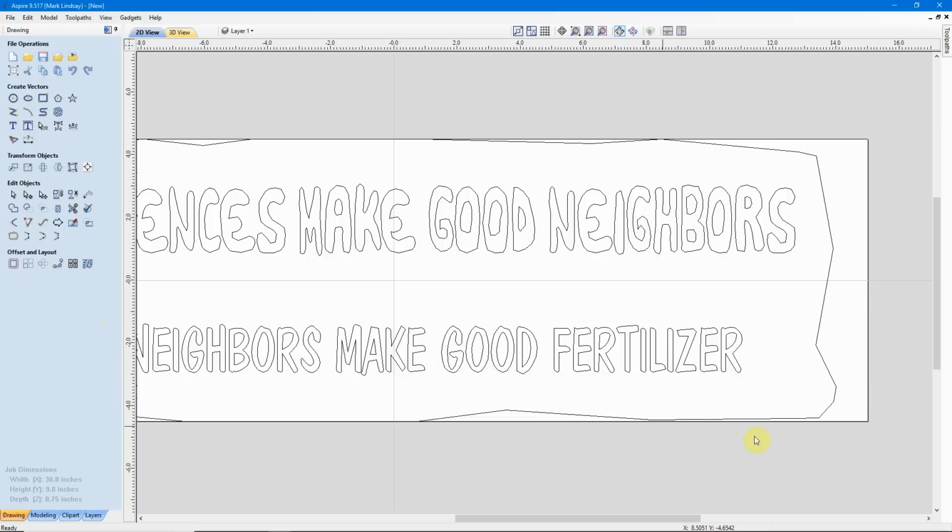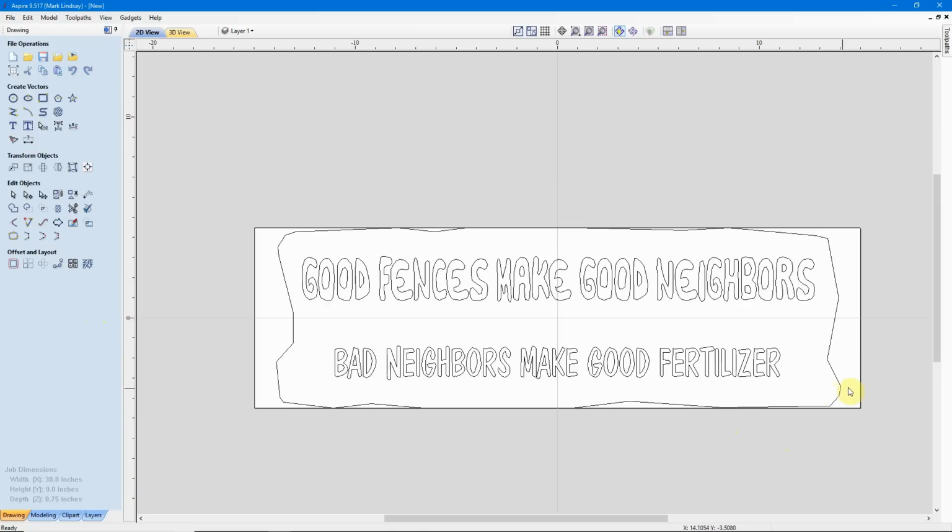So I close that. That doesn't draw any vectors. It doesn't do anything. So I know now that with this an inch away from the edge of my material, I can put a screw down in this corner and my 1/4 inch end mill can come right in here and cut, and I'll be just fine. Let's go ahead and calculate some toolpaths and see how this looks.